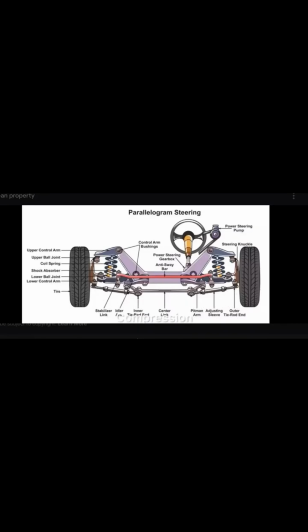1. What are the 4 strokes of an internal combustion engine listed in order? Intake, compression, power, exhaust. 2. In what position are the valves and piston during the intake stroke? Intake valve open, exhaust valve closed, piston moving from TDC to BDC.